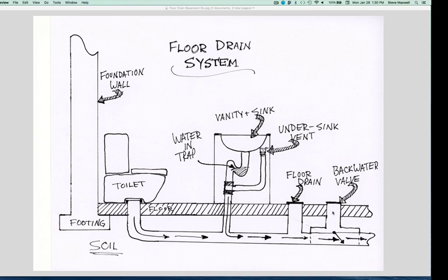So a backwater valve is definitely very cheap insurance. You're going to have to break through the concrete floor or have someone do that to install it, but it's not as big a deal as it sounds. So that's thing number one. Now let's just say you want to install a bathroom in your basement. It's very common. You are going to have to tap into this existing line.